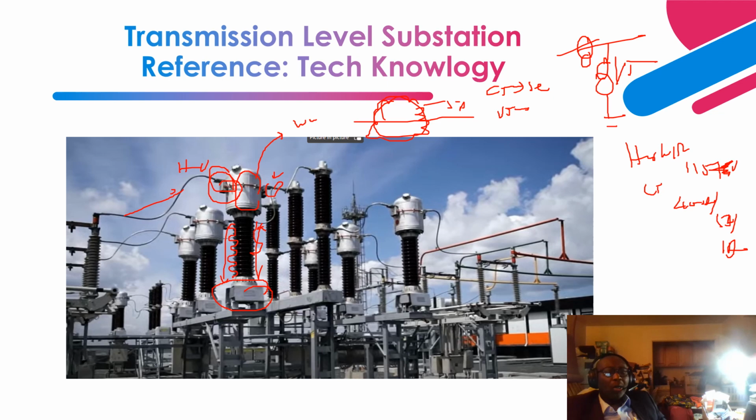Okay. On this side is a circuit breaker. This circuit breaker is called a live tank circuit breaker. There are two types of high voltage circuit breakers that you see: dead tank circuit breakers and live tank. So this is typical of a live tank circuit breaker, and inside this is the interrupting chamber. This one is just a support insulator, to protect it from the ground plane.